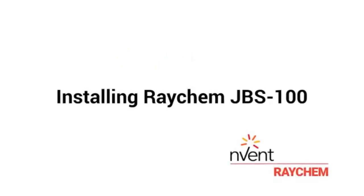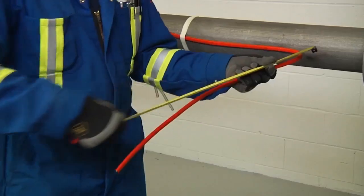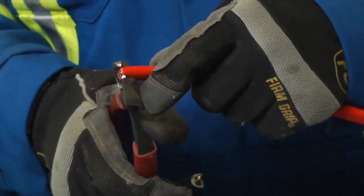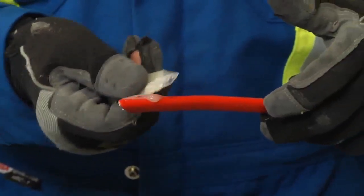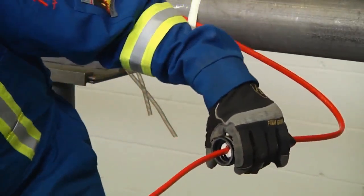Installing nVent Raychem JBS 100. The nVent Raychem JBS 100 is a power connection kit for a single heat tracing cable. First, allow about 24 inches, 600 millimeters of heating cable for installation. Cut the heating cable end at about 45 degrees. Apply lubricant for easier insertion into the stand. Push 18 inches, 450 millimeters of heating cable through the stand.